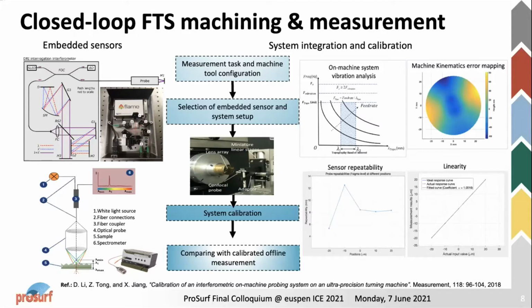For our ProSurf applications, single point alignment sensors offer the best feasibility, and we have tried both a commercial chromatic confocal sensor and an in-house developed dispersed reference interferometer sensor, and integrated them into the machine tools for both freeform surface machining and structural surface machining. Next, after you find the right sensor for your application, the second question is how to integrate and realize on-machine surface alignment.